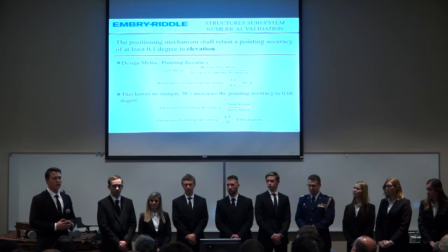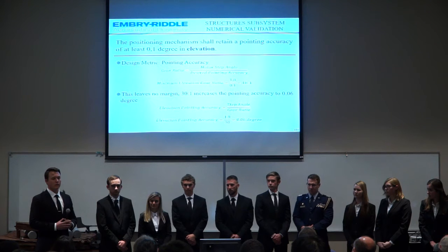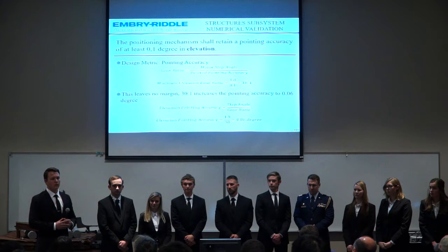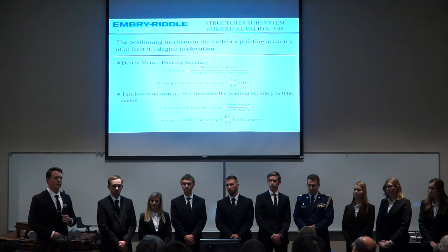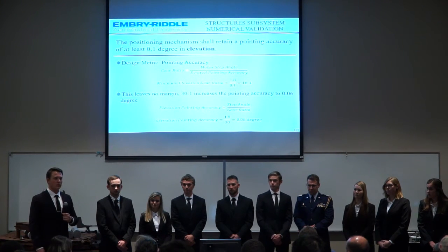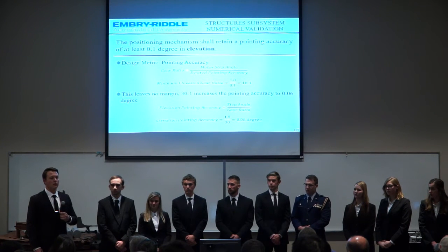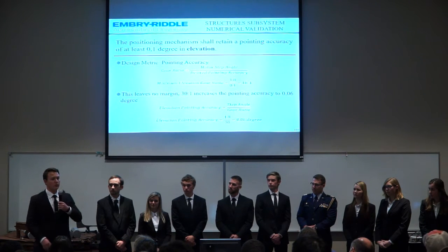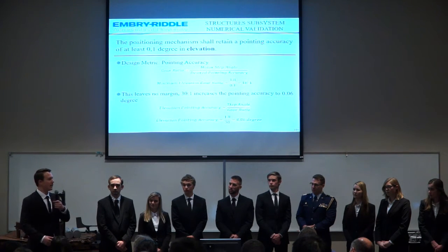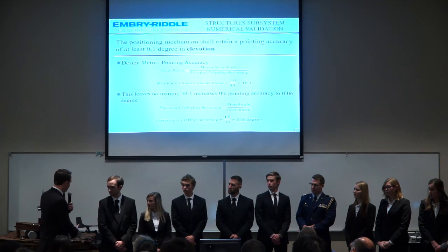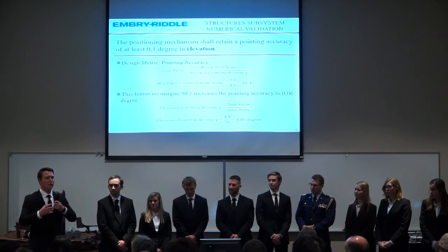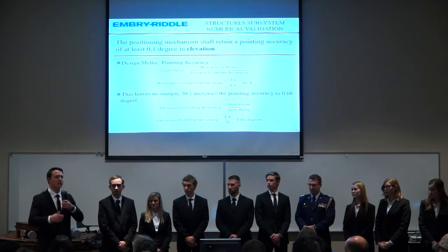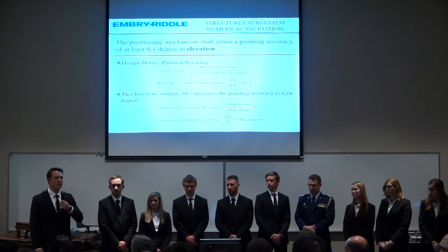Now, the other question is the recoil of the platform. So the platform is just going to sit on the ground obviously, when you shoot the projectile, there is going to be a recoil for the platform going to move backwards. How are you planning to address the issue? So when we were testing the structural stability, we had applied the recoil force into the maximum force that the feet could have, and in the feet, which are modeled on here because we made it out of cardboard, there will be a giant rubber foot that it will sit in to prevent any slippage on the ground. It's based on friction, basically. Yes, it'll be a friction-based system.